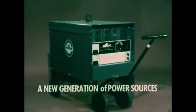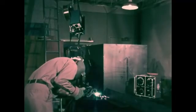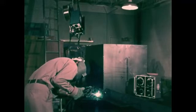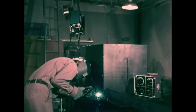A new generation of constant potential or constant voltage type power sources have added even greater convenience in applying short-circuiting metal transfer. A major innovation is that slope or restraint of the maximum short-circuiting current and its rate of response is controlled electrically within the power source. Secondly, welding may be done with a remote control system at substantial distances from the power source itself. This is a typical situation that might be encountered where two different welding conditions must be met.